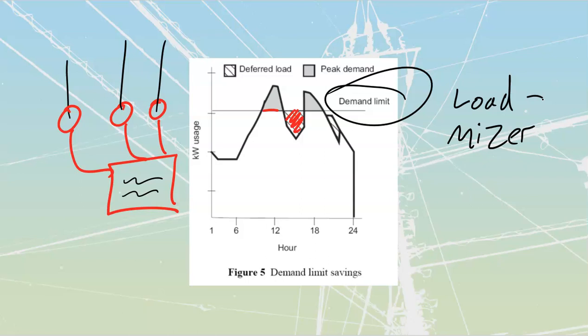Where we see these used now is in the advent of electric vehicles. Because electric vehicles take a lot of power to charge up, particularly if you've got a fast charger, so you can't be running everything. You've got a lot of people that have a house that might be sitting on close to 70, 80 years old. It's got a 100 amp panel inside. Maybe it's a heritage home, so they can't do a massive renovation to it, but they want to buy an electric vehicle. And in order to charge that, they need to have a 30 amp charger. And we just cannot add that onto that existing 100 amp panel that's already probably maxed out.